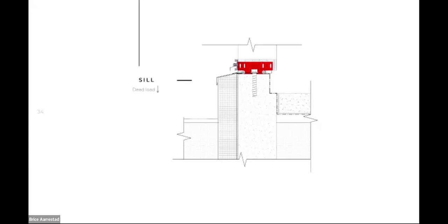So the curtain wall system comes in, various control layers and sealant are applied. The glazing system comes on top of that, and that's the finished system along with some interior finishes coming in. There are a lot of ways to do all of these details, to try to either conceal the curtain wall anchors or to have the back members align with the floor line, or a variety of other ways that we can detail this. But just showing you some standard details to give you an idea of how the system works.